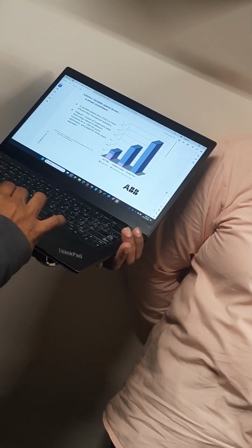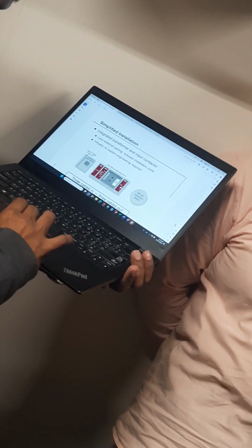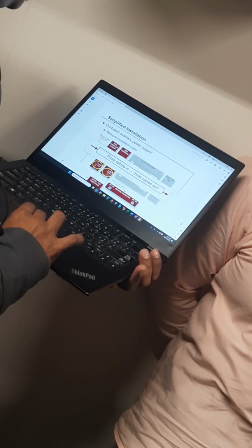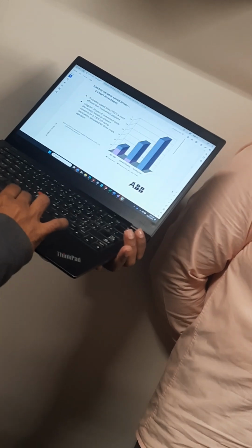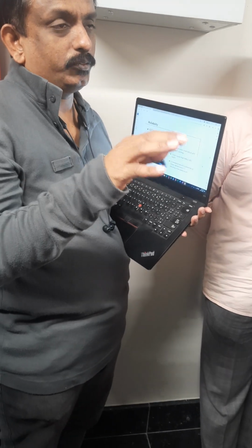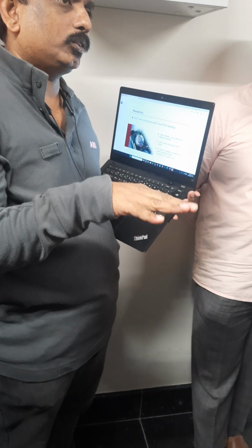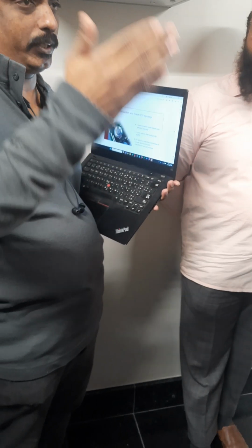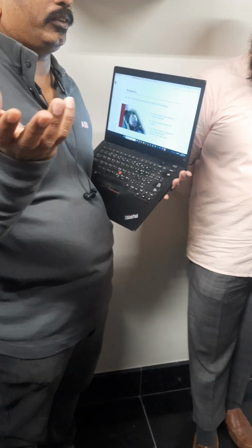And actually, we have planned for the operation and maintenance. I don't have much to show you here. Inside the drive, if the pressure is high, the drive will be tripped. If the pressure is low, the drive will also be tripped. It's based on filter cleaning or filter presence. If you remove the filter, there will be a pressure loss and the drive can be tripped.